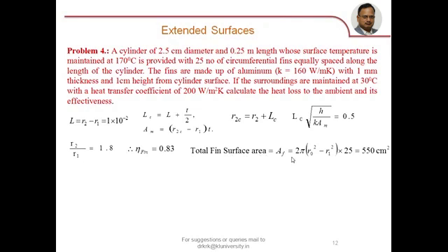The total fin surface area is 2 pi into R2 square minus R1 square into 25, as 25 fins are there, which is equal to 550 centimeter square.